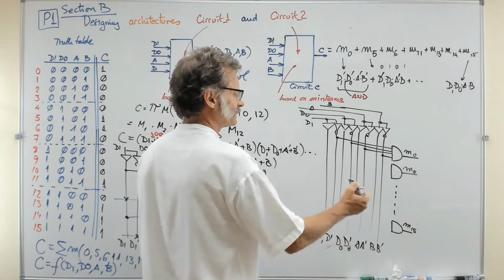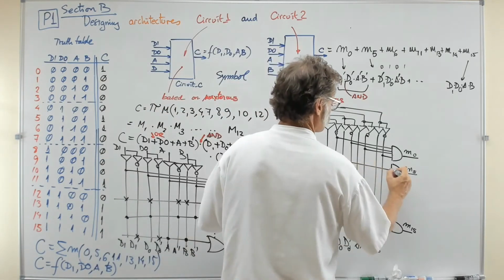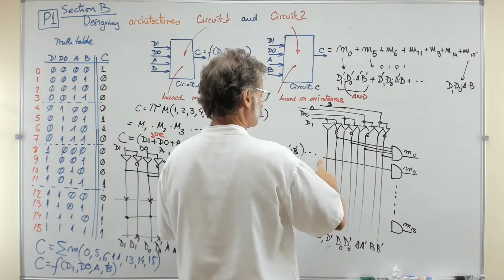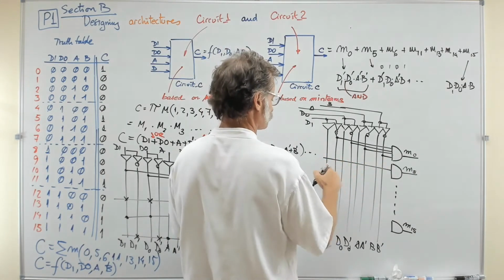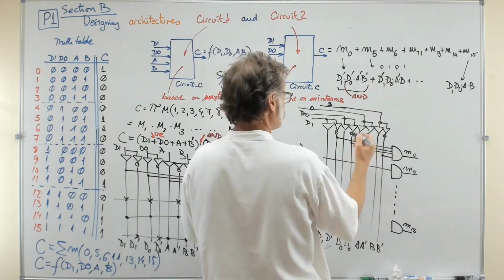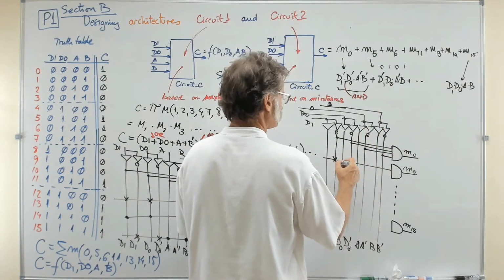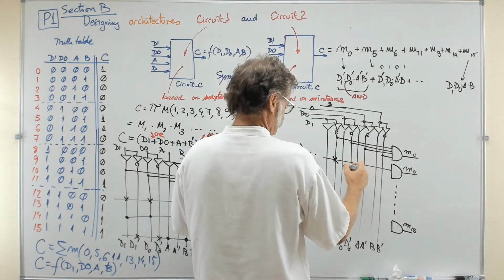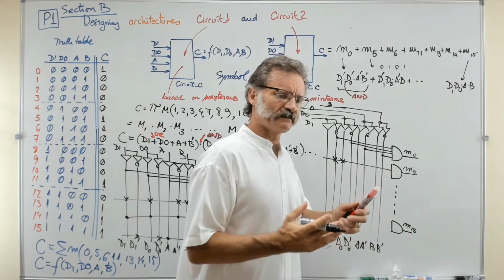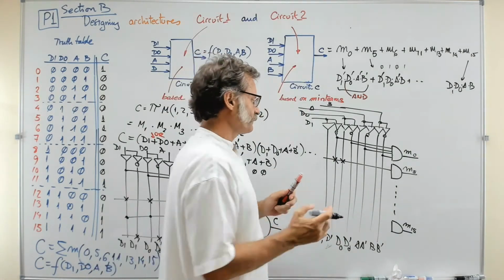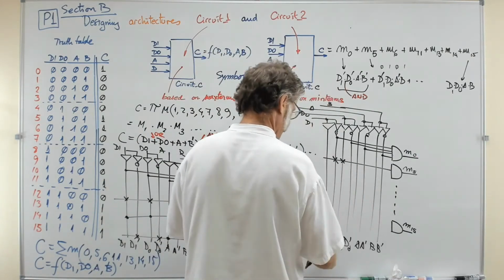And to generate the minterm 5, you can proceed in the same way. You can simplify if you like. Just a single wire and dots or crosses to represent what you are going to connect here. D1 not, D0. Okay, remember that those are minterms, so every minterm requires all the 4 variables to be synthesized correctly.